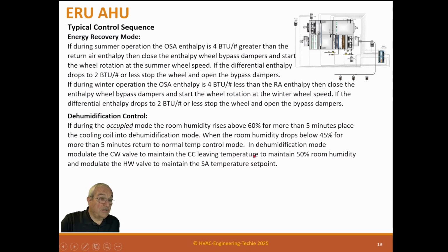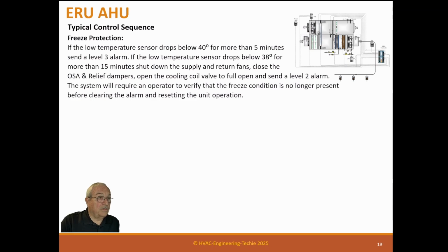Remember, dehumidification is expensive, but it's very mandatory. If you let the room humidity float up above 60%, you could be endangering people by the growth of mold. So you don't want to do that, and besides, it's uncomfortable. When humidity gets high, people get more uncomfortable, and they'll try telling you that the temperature's wrong, but it's not the temperature, it's the humidity. So you want to make sure you control high temperature conditions or high humidity conditions.